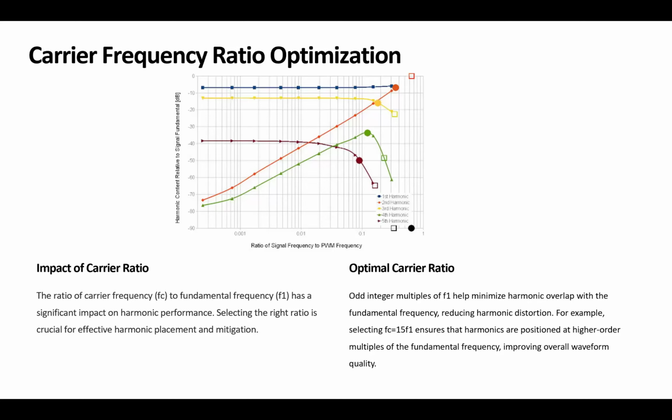So the first idea that we focused on previous session was okay, let's try to control the switching in inverters because we know the cause of those harmonics is the switching. So let's control the switching with different leverages that we have in hand on that control system in order to have a lower harmonic.